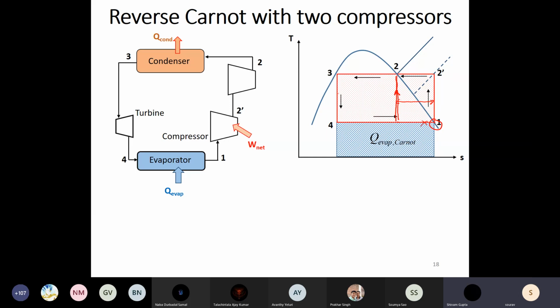The second thing is, I have already told you, when you try to compress the liquid and you do not have the requisite clearance volume, then you can have catastrophic failures of all the sealings that are there. So hence you would want to maintain the entry to the compressor in the saturated vapor region. It can be superheated vapor, no issues from the compressor life point of view.